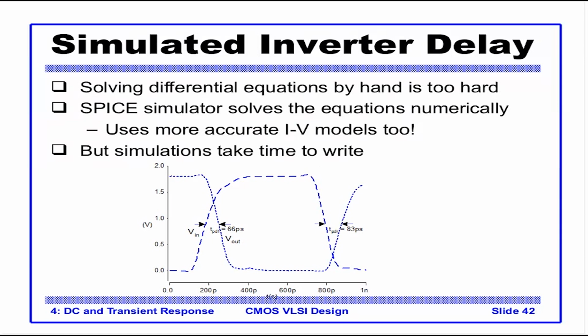So this is a SPICE simulation of an inverter. I would recommend all of you to do this yourself using the SPICE tool. Obviously, SPICE will not use your simple Shockley first order model or a simple alpha model. It will use a much more complex and accurate IV model. Simulations are not that easy to write, but once you are familiar, you can write a basic simulation. At least you can simulate a step response, or you can even simulate a step response in steps of 20% of VDD. You can do that easily.